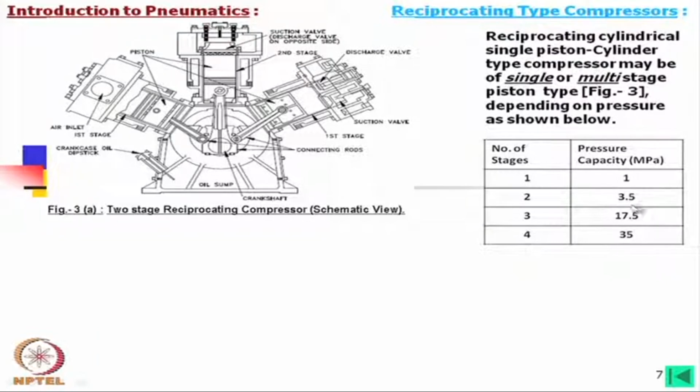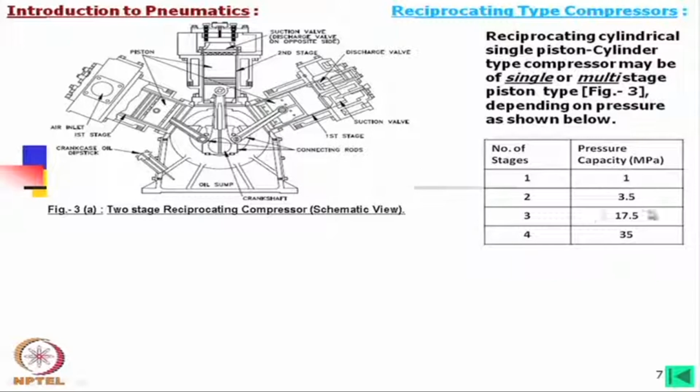Say for example, for a 2 stage system of 3.5, it is probably raised up to 1.5 only. Then that total compressed air, what the 2 pistons have done, that volume has reduced, so a single piston can pressurize that amount of air further to 3.5, and that is the second stage piston cylinder. Now the other details you can study on your own from this figure.